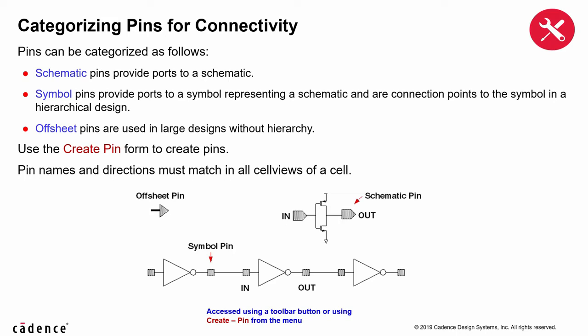Pins can be categorized as schematic pins that provide ports to a schematic, as symbol pins which provide ports to a symbol representing a schematic, and are connection points to the symbol in a hierarchical design, and as off-sheet pins which are used in large designs without hierarchy.